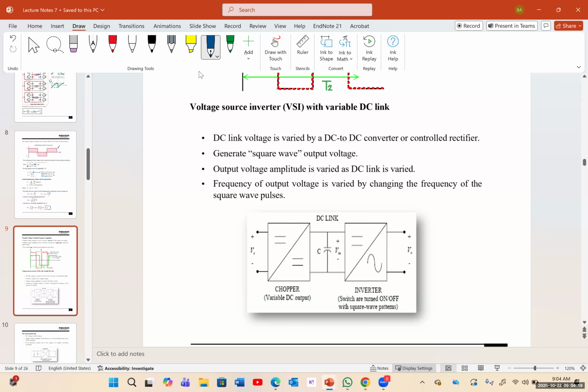The first frequency that you want to control, F1, is actually controlling the duty of the first one, and it's changing the voltage. The frequency that you're changing the second time is changing the switching frequency, and therefore it's changing the frequency of the system. So for the DC to DC link, when you change the switching frequency, you're changing the voltage. For the DC to AC system, when you're changing the frequency, you're changing the output frequency.